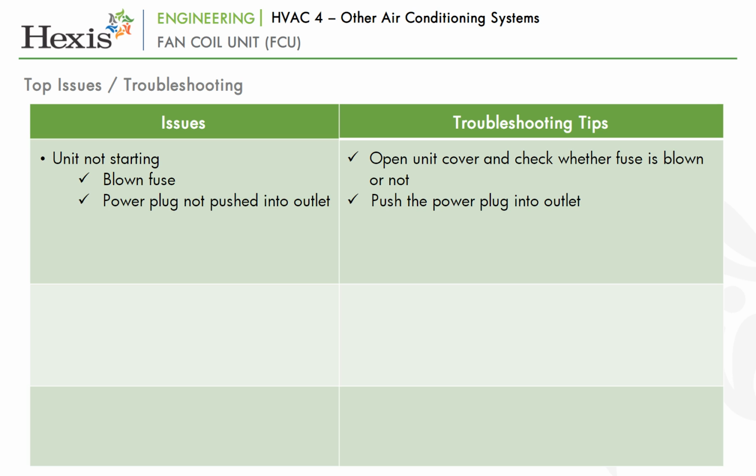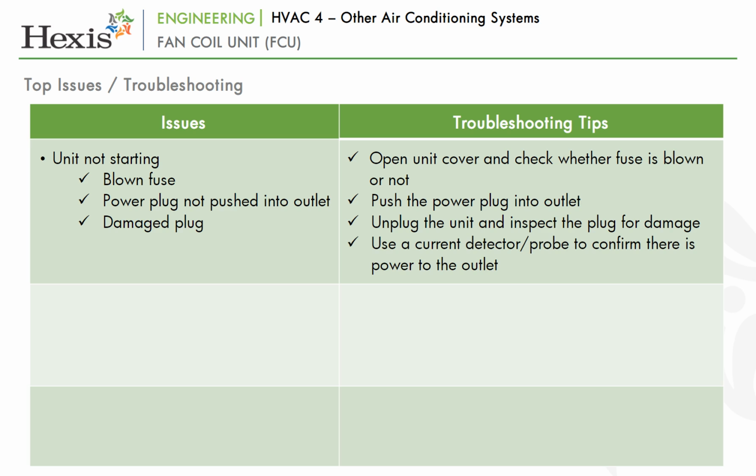Check the power plug. Make sure it is completely pushed into the outlet. Unplug the unit and inspect the plug for damage. Use a current detector or probe to confirm there is power to the outlet. Look at the delay timer to verify that it is set correctly if all power checks are good.